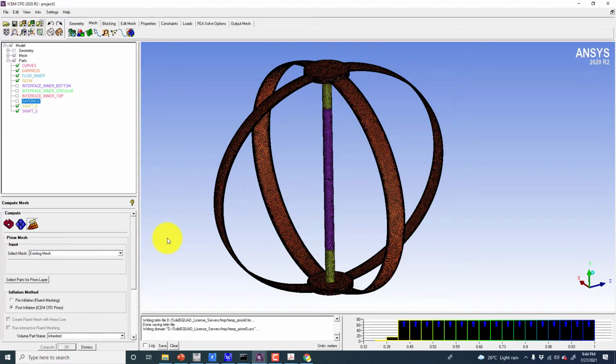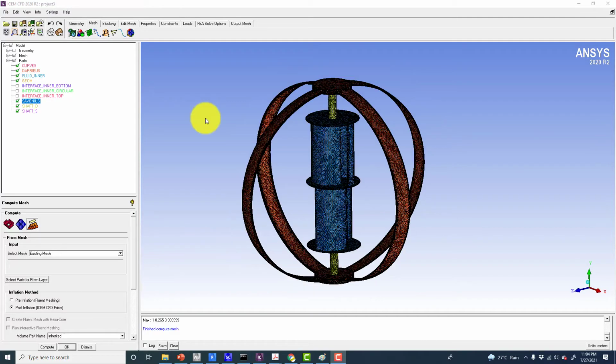I will split the 3 layers into 9 layers and rearrange them so that we have a smoothened mesh, in the proper order, increasing from the lower sizes towards the wall to higher sizes towards the tetra mesh in the domain. I will wait for this to be completed, and it will take some time, maybe 15-20 minutes, and after that I will come back.